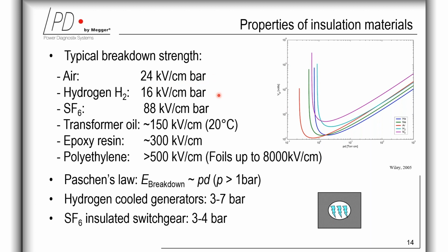Other gases, such as hydrogen and SF6, can become a good insulator if used in compressed form, such as in gas-insulated switchgears or gas-insulated lines. And the breakdown strength of SF6 gas with 4 bar at relatively high pressures is about 3 times higher than under 1 bar.